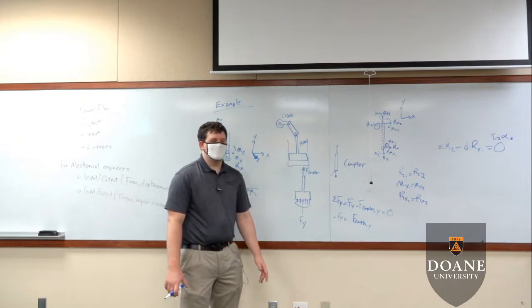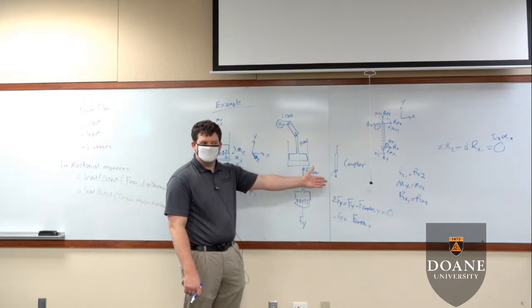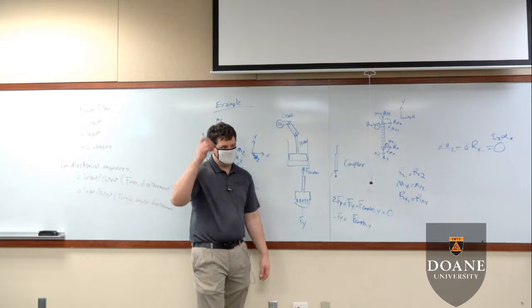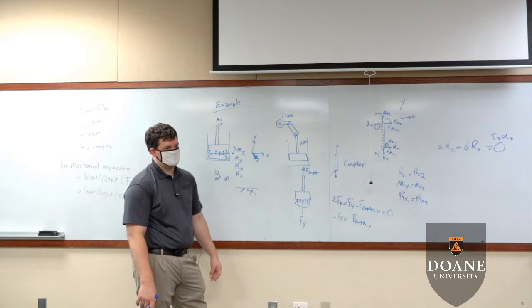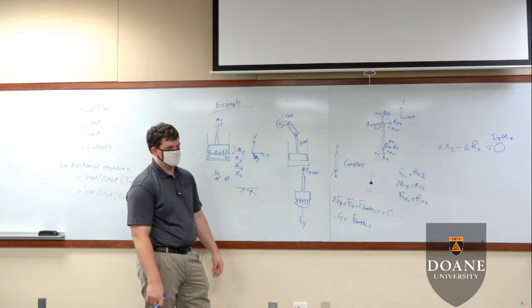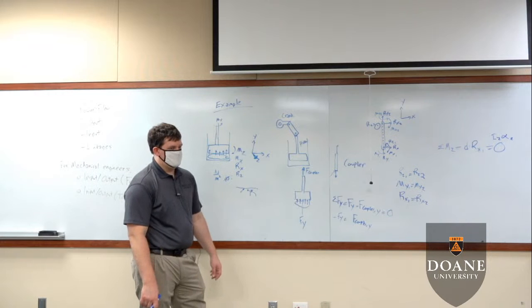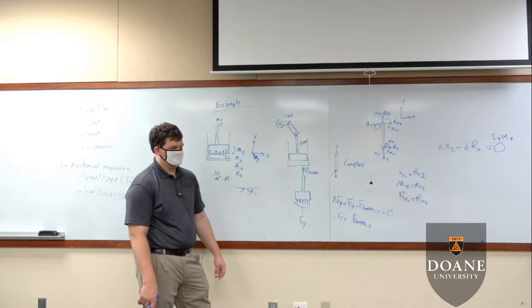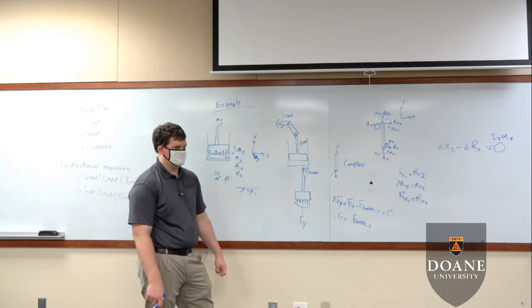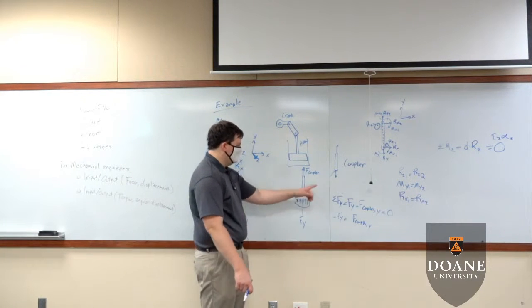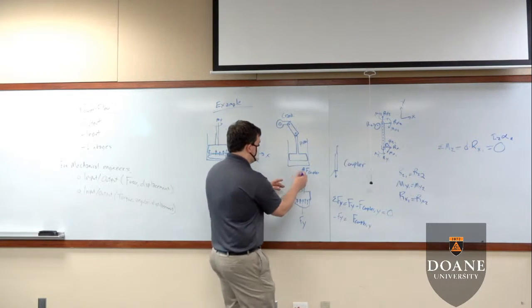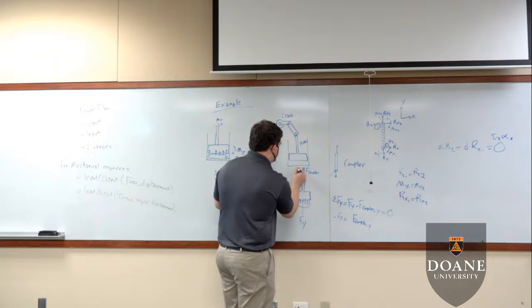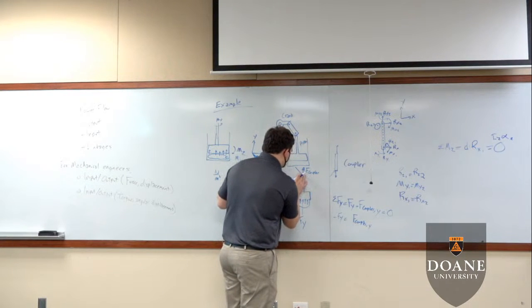Okay, so your argument for why it's larger, why is that the case? Because the Fy of the coupler is one of the components of the actual force, and that component has to be the same as the Fy coming from the piston. So if we add the two components, it's going to be larger in the actual. Okay, I like that explanation. The thing is, this force, if we're going to exert it in the same direction as the coupler, is going to be like this. I guess I'll draw it the right way.